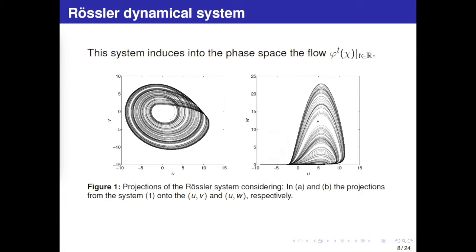On the right-hand side, the values for the state w range between 0 and 25. Considering analog components such as operational amplifiers, these values exceed the voltage limit that the components can process without reaching saturation. Therefore, scaling of the system is needed before the electronic implementation.